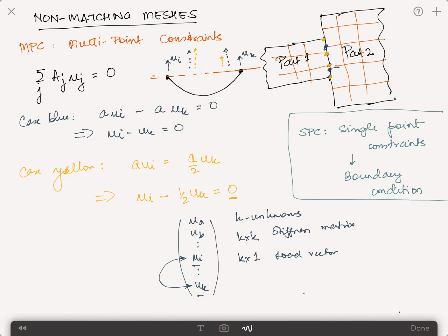So in the end, if I'm going to do any manipulation on my displacement vector, the same manipulations have to show up in the stiffness and in the load vector. Of course, for the load vector I can just keep adding or removing certain locations, that's fine. But with the stiffness matrix, this is a serious problem.